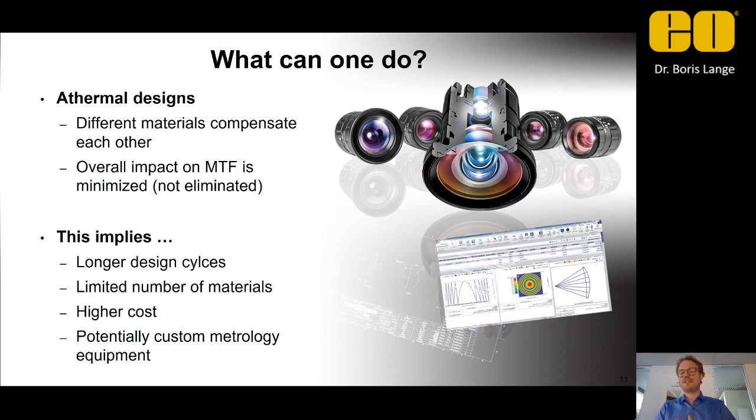Select different materials for the metal, carefully consider how you seat the optical elements. Maybe you also cannot use certain glass materials, even if you would like, because you need something else in there that has a CTE that compensates the rest of the system. So that's all the fun that's involved when you do this during the design time.